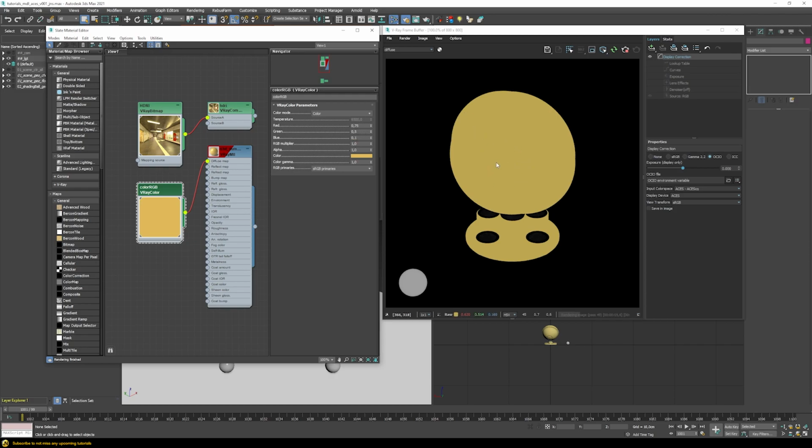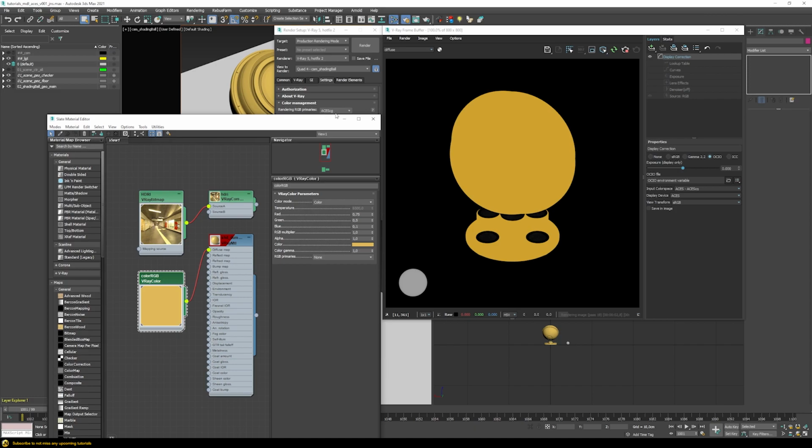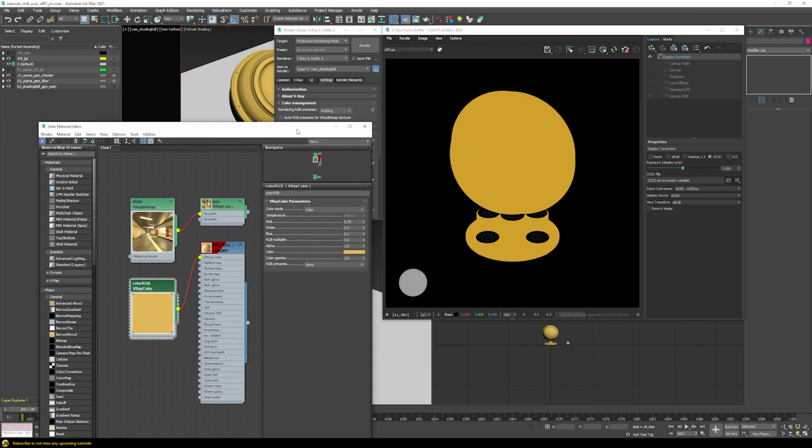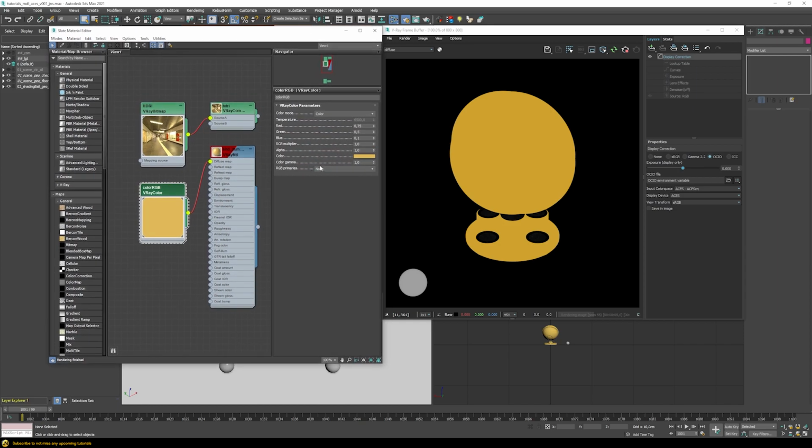They are not rendered like this because those values come from sRGB color space, but in ACEScg, those color values would be translated into those color values here. And then if you go to none, we just double confirm that basically now it uses ACEScg color space because that's what we set up in here. But in our case, let's just make sure to switch here to ACEScg and then we can move on.